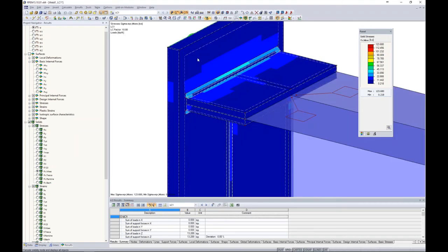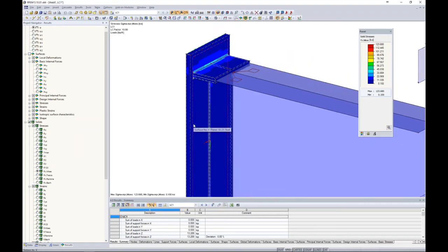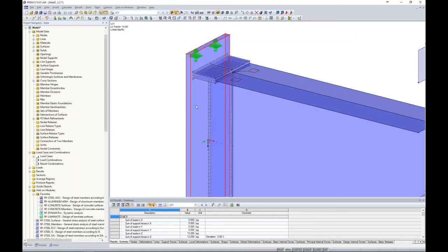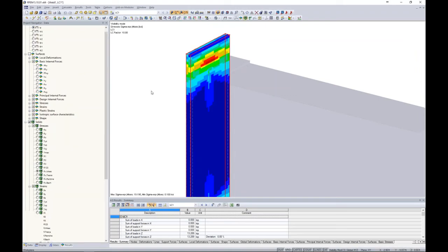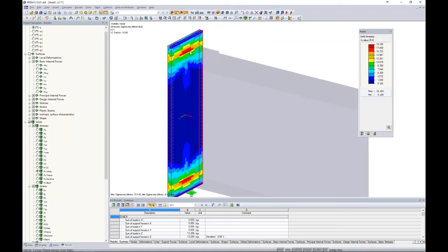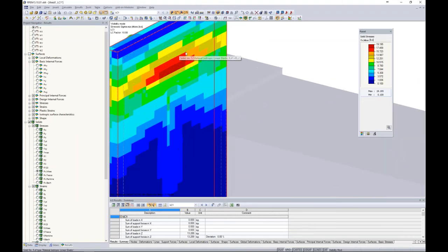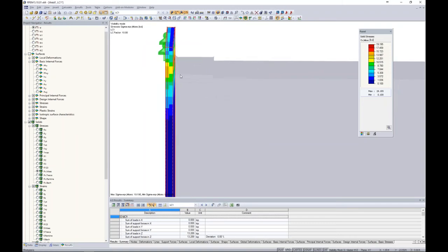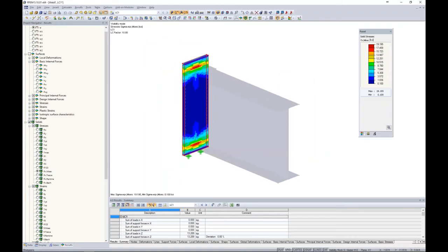So we can also take a look at our plate element. So let me cancel out of this visibility mode. Maybe we select, let's see, just our solid, create a visibility by selected objects, view our results again. Again, this is just von Mises stresses, and we can see the points of high stresses here, right where that weld is framing into the top of the flange and bottom flange. So just another approach for a welded connection, independent again of contact solids.